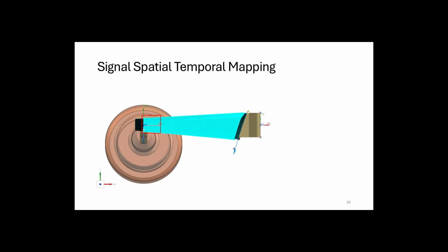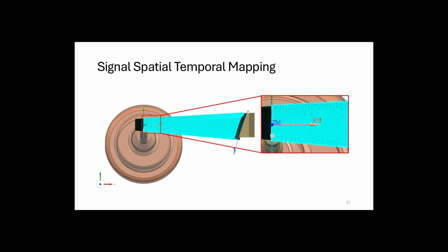And so to summarize the database that was created, we have three different signals we focused on, those being load, encoder position, and control position, across the 5 different axes, so X, Y, Z, A, and spindle. And then we have 2 different operations. And so we have a summary of how many vectors were actually generated per signal per axis, including the spindle. So for the blade profile finishing, we have around 50,000 vectors for a database, and for the shoulder front finishing, we have around 13,000. And if you extrapolate this across 10 different parts and 15 different signals, we have around 3.2 million vectors that we need to compare to for our final prediction step.